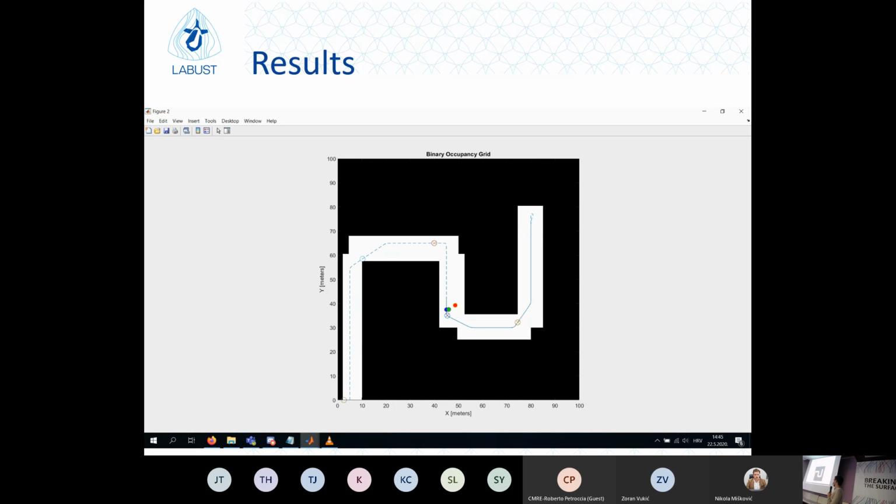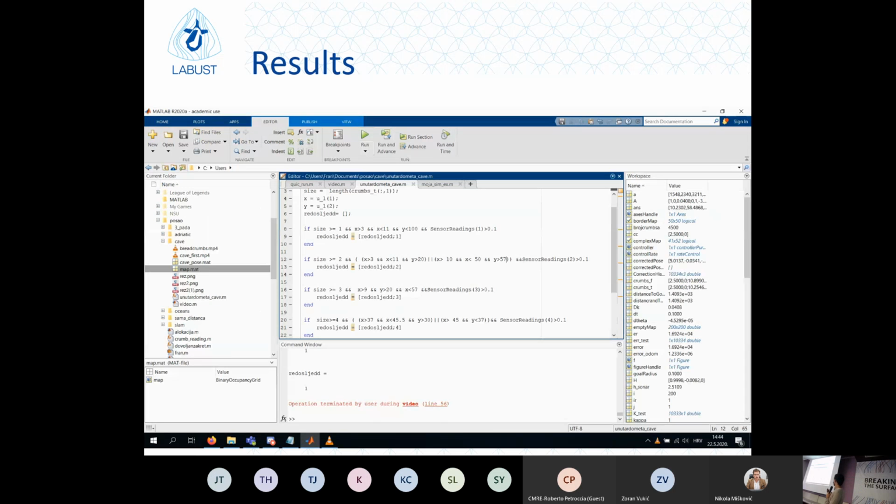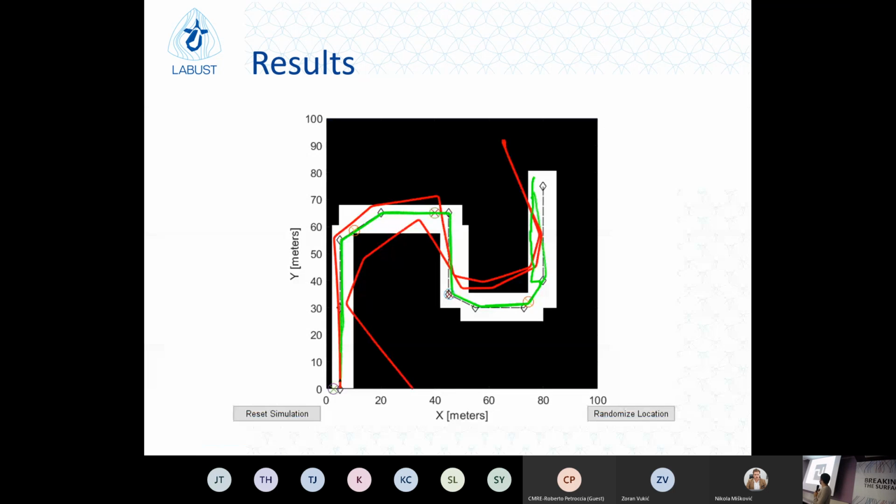And this is the intended solution, because on the way back, we can use old beacon positions to ensure that the AUV returns straight to the location. And you can see that right here. At the end, it drifted apart, but then when it came here, around here, into the range of this beacon, which had very fine positioning, very fine observability, it bound the error right back on the track. So I also forgot to mention, but when it leaves the site of the beacon, it pretends that it cannot access that beacon, of course.